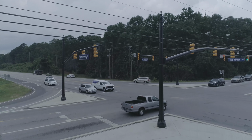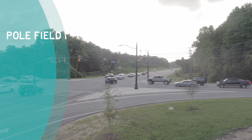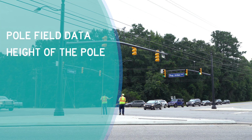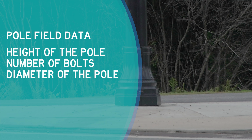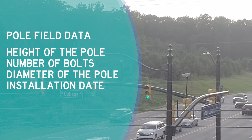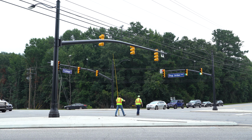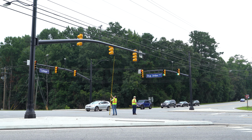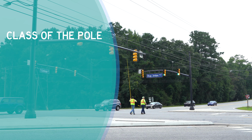Another common operation is the adding or editing of poles. Let's gather our field data first. We will need to know the height of the pole, the number of bolts used, the diameter of the pole, the installation date, and the pole type, including aluminum, concrete, fiberglass, steel, and wood. We will also need the class of the pole and a description of the pole.